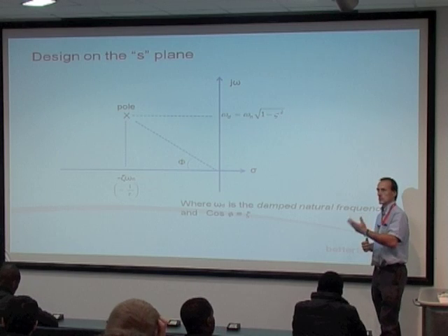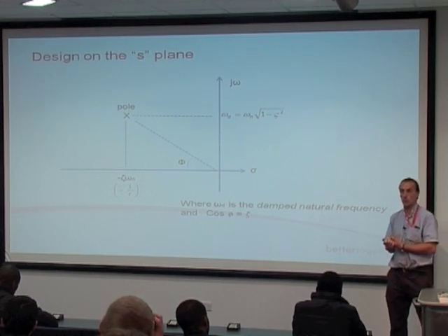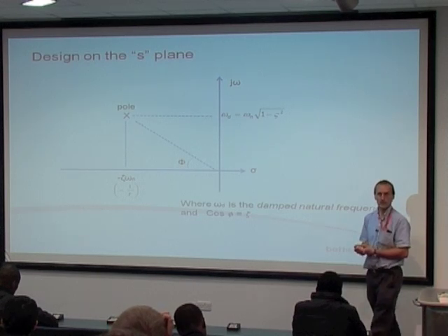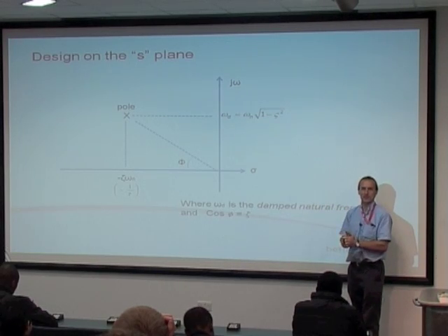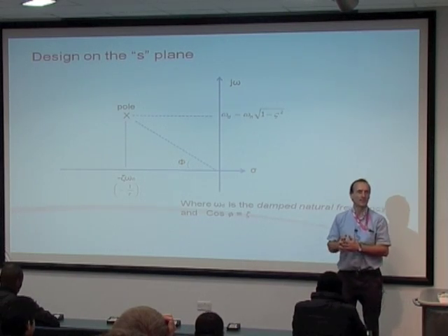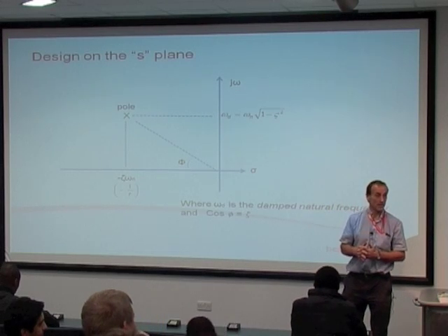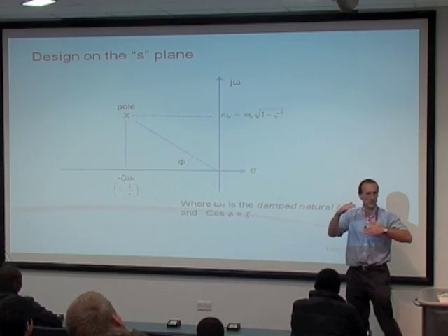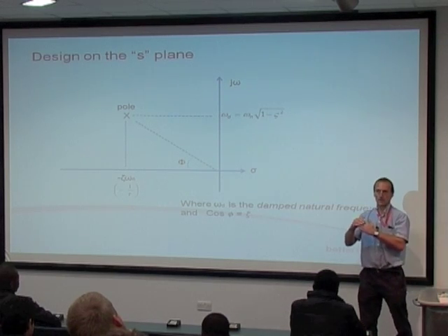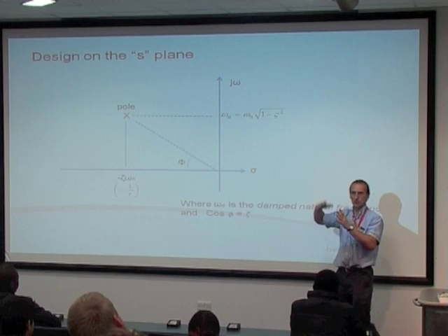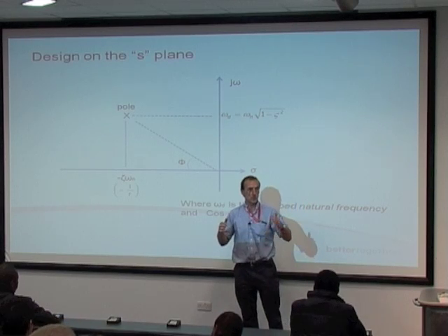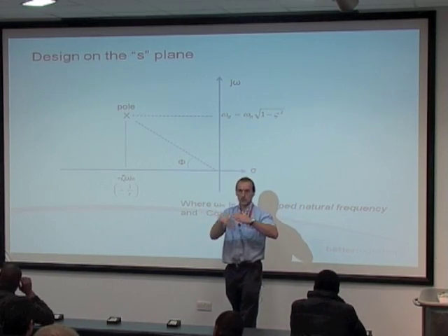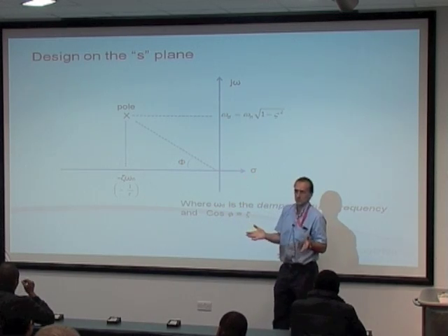The other performance definition that we used was a thing called rise time. I'm going to ask you again. Anybody remember what rise time is? No, that's closer to settling time, I'm afraid. Yeah, the time it first reaches, or within a particular percentage of the desired value, regardless of whether it then oscillates beyond or underneath that. So the time to first reach that value, we tend to define it as to go from 5% to 95% to cut out the flat bits at either end. But it's roughly that.